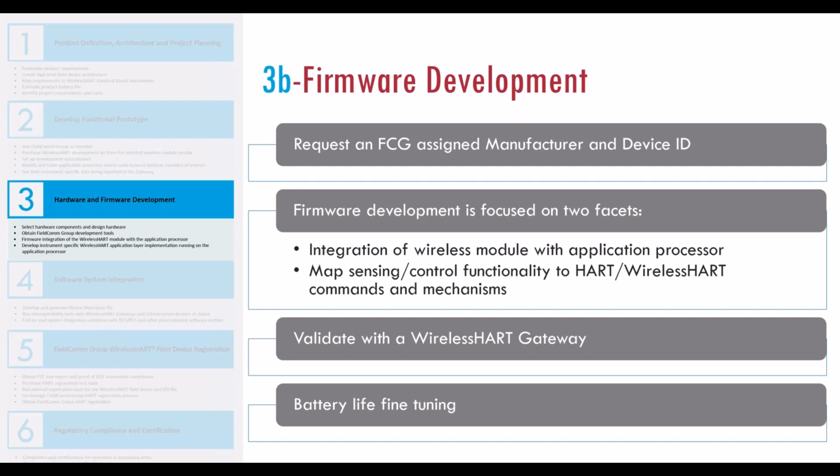Next, you would validate your firmware with a WirelessHART gateway and ensure that your process values are being periodically and reliably reported to the gateway. And it is also here that you would do your battery life fine tuning.